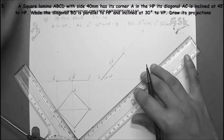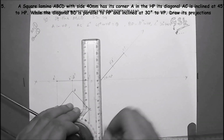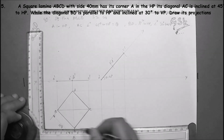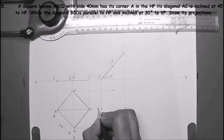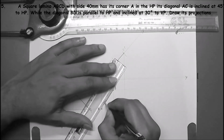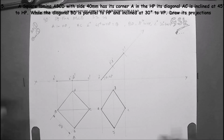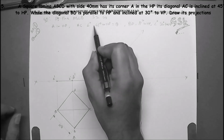Now project this down for getting the top view. And project this side. So these points, this is A, B, C and D. So our diagonal AC is inclined at 45 degrees to the HP, and we have finished this one.